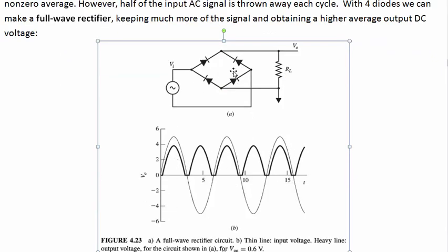Now the disadvantage of the full wave is that every path through, you've got to pass through 2 diodes, so you drop double the diode voltage. And so you wouldn't actually want to use a full wave rectifier if your input voltage signal is too low, but for an appreciable input voltage signal, this is a pretty good way to do it. How does this work? Look at this circuit here. There's no connection at this spot, because there's no little black dot at this connection. This just means the wires are passing over each other. These wires are connected though. This is connected, that's connected, that's connected.